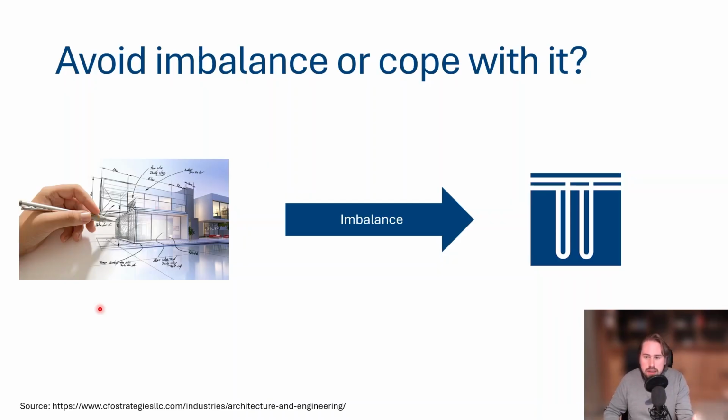Do we use active or passive cooling? Which heat pumps we use, modulating or not? Are the heat pumps selected in cascades or not? So this all has a certain influence on the final imbalance, the amount of energy we are exchanging with the ground. So this is what we can do to avoid the imbalance.